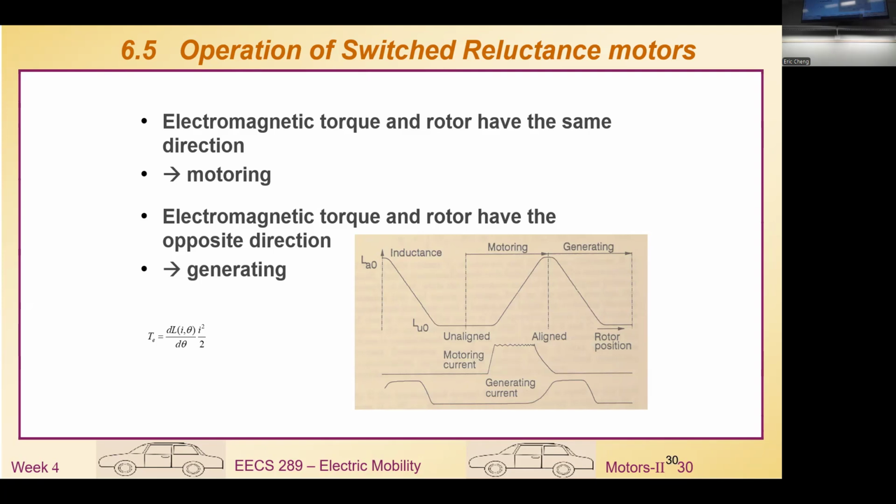So in this part, it looks more like motoring, with the power from DC to the motor. This part is so-called regenerating, where the rotating mechanical dynamic returns energy to the battery. So we can control how much we turn on and how much we turn off in order to control the motor, more like motoring or regeneration. You can control the motor for more power, like a motoring torque, or reversely, the reverse torque will become braking. So that's how they basically operate.